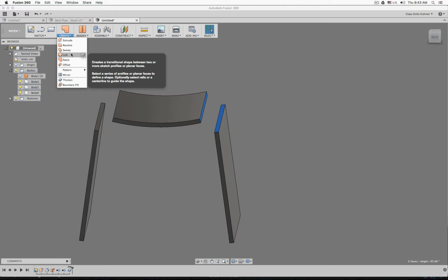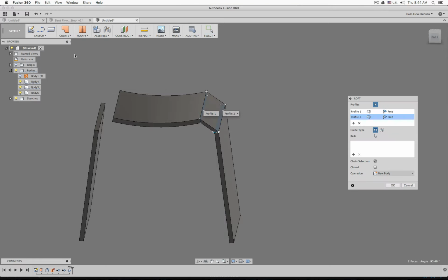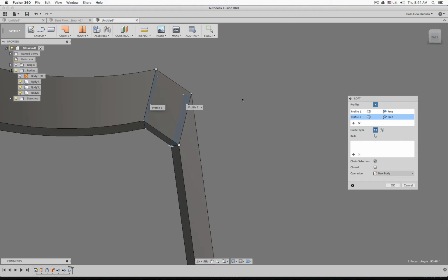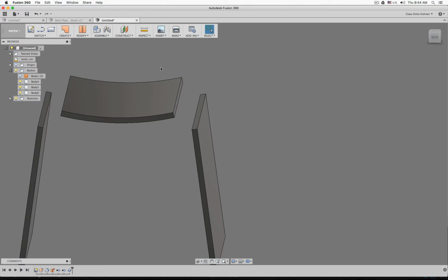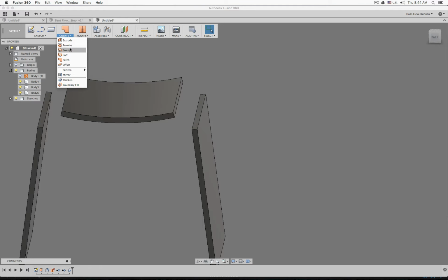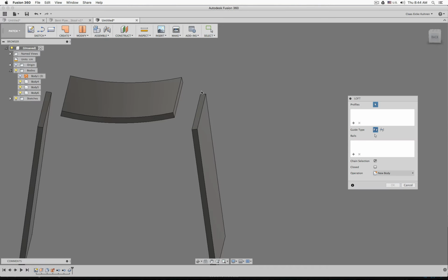And in Fusion, that is part of the Loft command. So the nice thing about Fusion is they don't bombard you with menu options and different tools. They have everything more compact and have more powerful, fewer tools. Okay, so we can click OK. You see I had those faces selected. If you have no face selected, click Loft, and then I start from the top to the bottom.